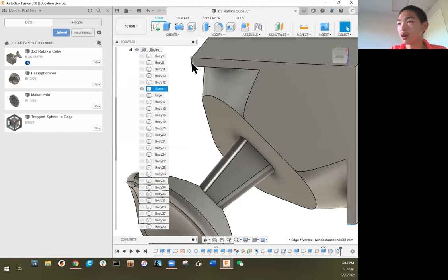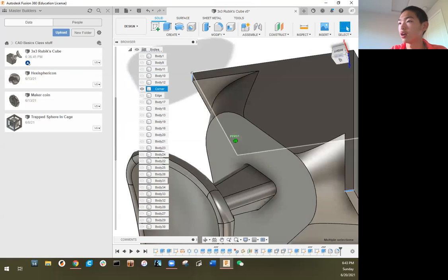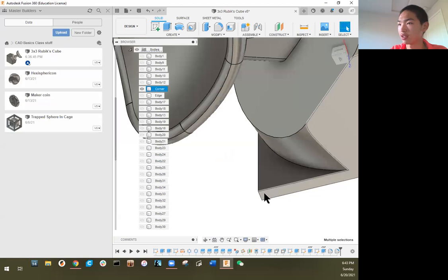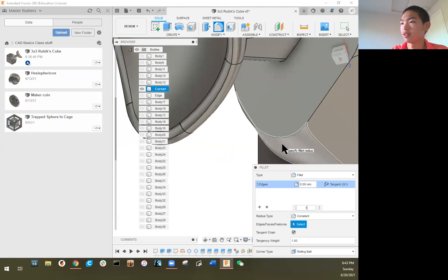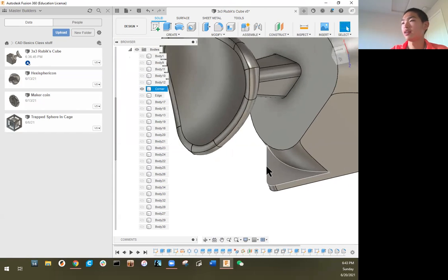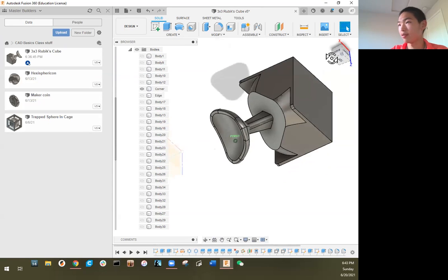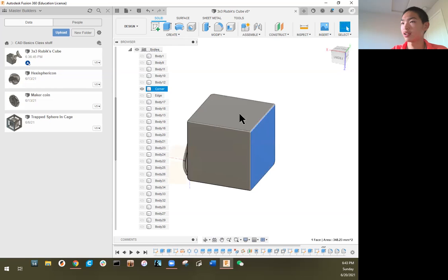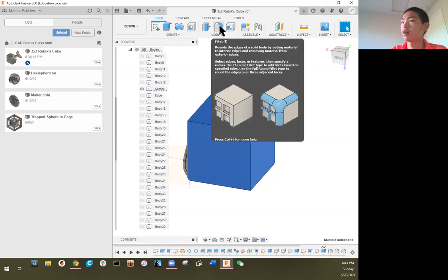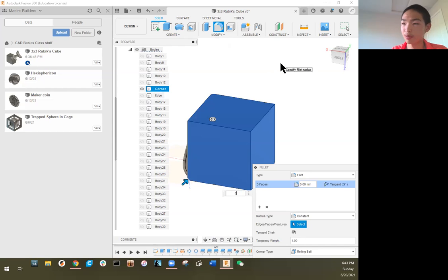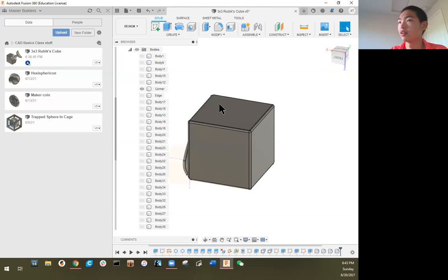of the extra outer surface thing we just created. And then we can do 1 millimeter. And then after that, we want to fillet all the edges of the corner. So we can just click on the top 3 faces of the corner and then we can fillet and do 0.5 millimeters. And it'll just fillet all the surrounding edges of those surfaces that we selected.